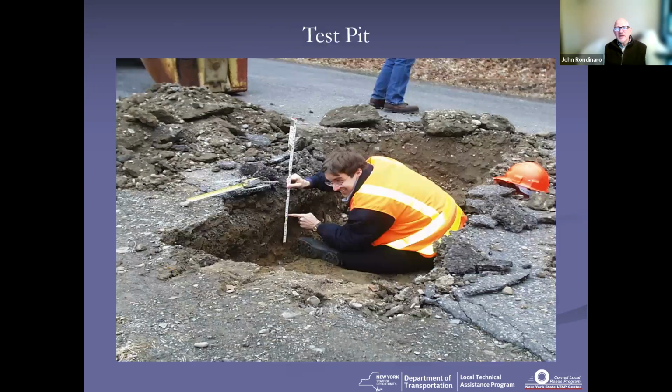And then last but not least, I think we might recognize the gentleman in this slide. This is the tried and true method. A test pit is going to allow you to get down deep, get down in there and really see what's going on in the underlying granular layers of the pavement. In this case, our director, David Orr, recognizing him. This is when he was a younger lad, but he looks like he's really enjoying himself, getting right down and dirty in that test pit.